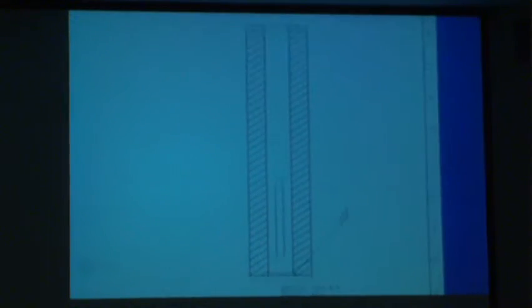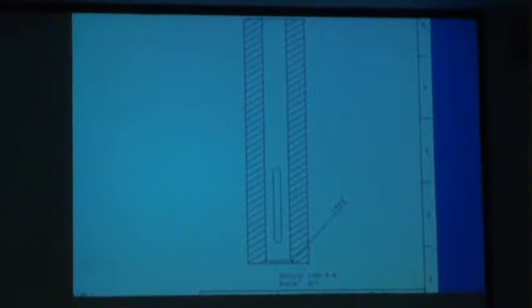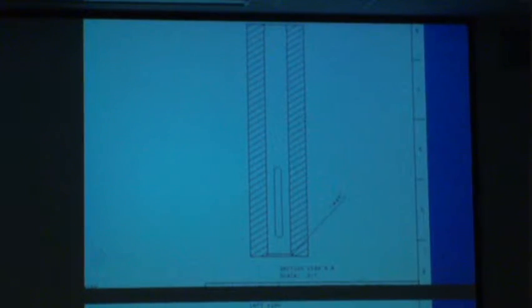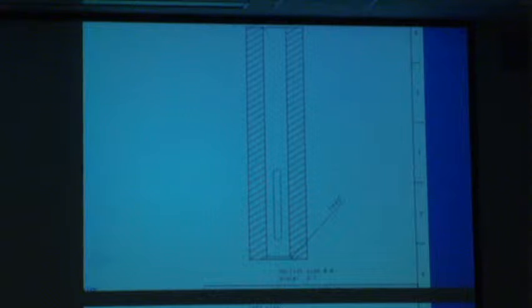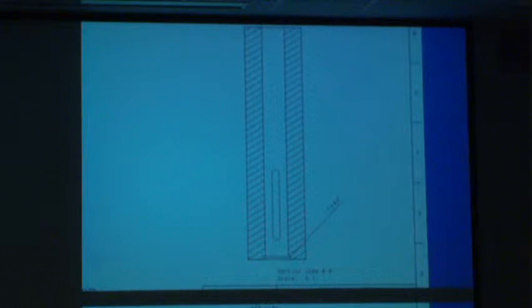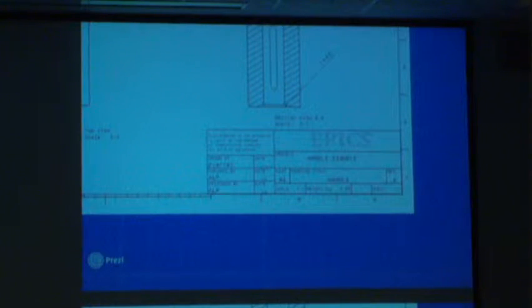Okay, and then here's that section view. So where you see the hash marks, that is what would be solid where you sliced the section view, and what is clear would be the solid material behind it. So that's where you're looking into the part. So this would be the walls of the handle. You can see through to the slot. Views like this are really good for things you can't see in any of the other views, like this chamfer that I've put down here in this sleeve. So I've got a 1 millimeter by 45 degree chamfer. You couldn't see that in any of the other views, so the slice was necessary. And there's a section view tag down at the bottom to show you where that is. So that's the kind of basic views of a print.